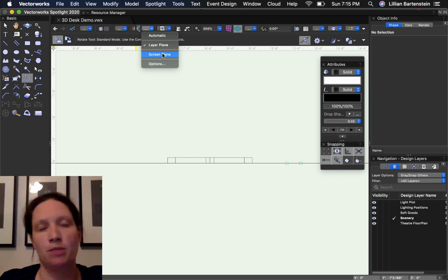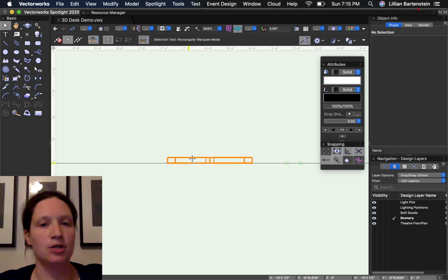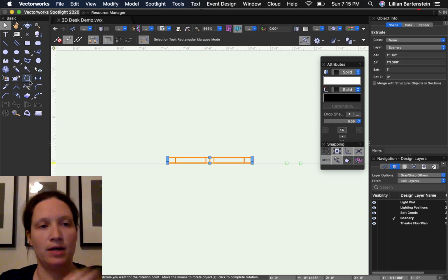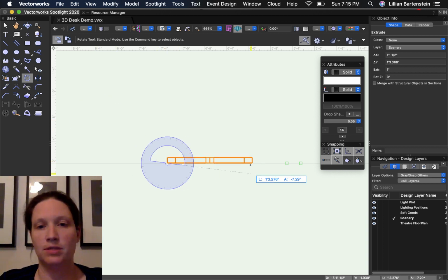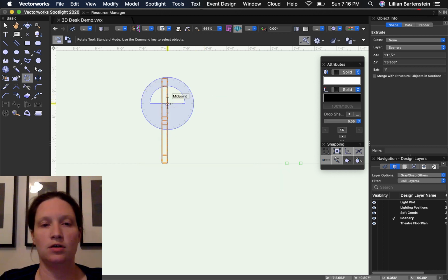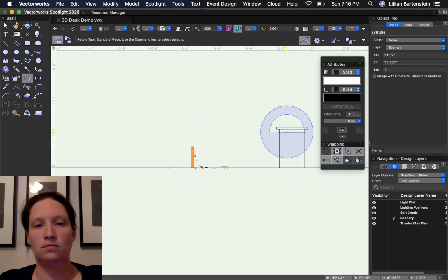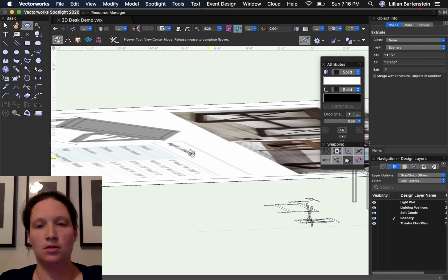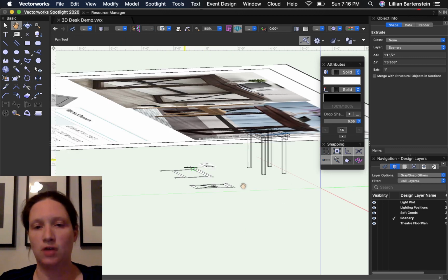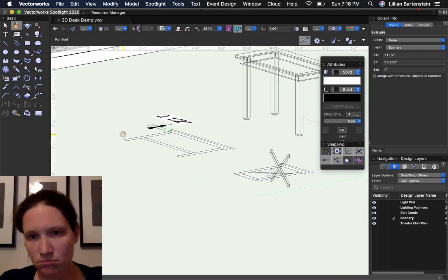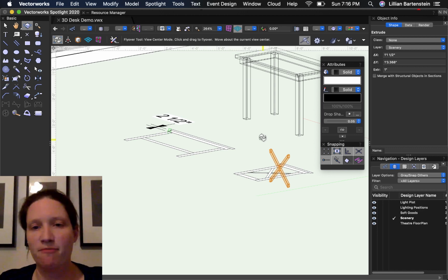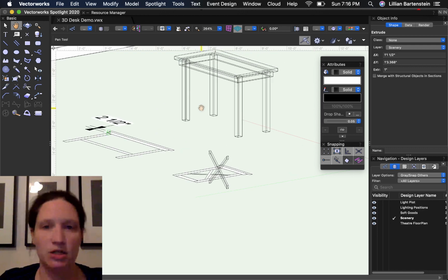If you change your working plane to the screen plane, now, once you've picked up an object like this, you should be able to, relative to the screen plane, rotate it into the vertical position. Clicky, clicky, vertical. So now, in our little world, we have a tiny crossbar. Now, I may not have been in the correct orientation. No, I'm good. Okay, so now I have my little crossbar that'll fit in between my 2 legs.